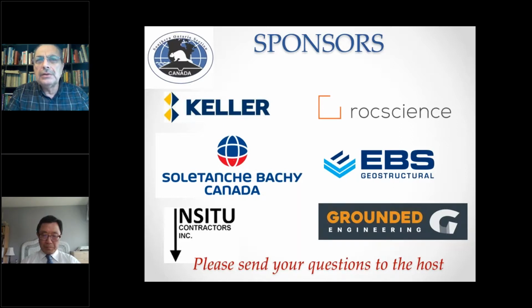And also I said it's because of low slump. So if you have low slump, you may have a honeycomb void structure within the concrete. So if you have a free fall of concrete, first of all, we do not use a free fall of concrete into slurry or into water. It should be a dry hole. So if it is a dry hole and you have enough slump, you will not have this problem.